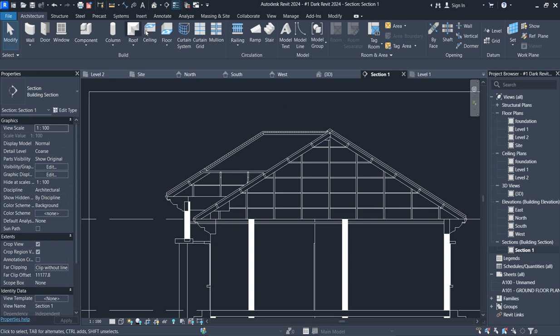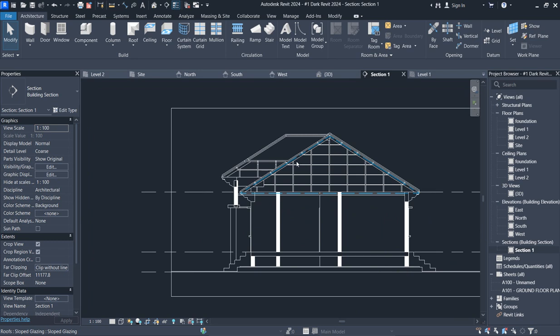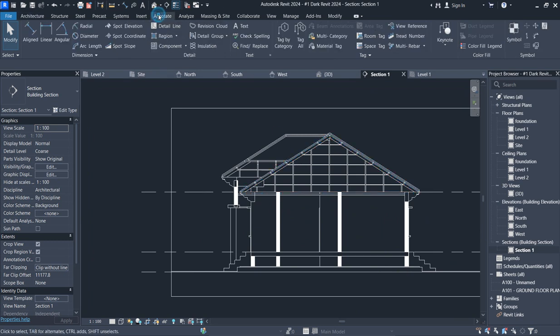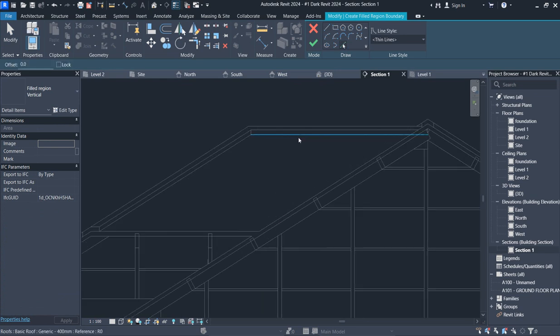So what you need is to bring annotation to this place. So you're going to do the same thing for all the areas that you have. So you remember this is the reference area. So this is the place we want to use the section, and this is our concentration because of the section development that we are doing here. So you click on annotate. So go to region and say fill the region. So you fill region by selecting this space.